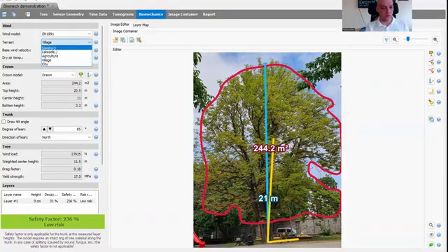I wanted to show the effect of changing the terrain. If I change to a seashore, the model will calculate with larger winds. The EN standard defines different slices for different heights, and each slice will get the wind speed from the top of the slice. There are several things in the standard that are trying to overestimate the wind load.